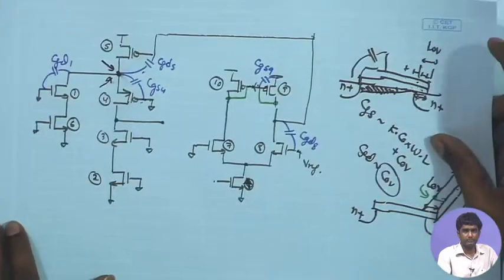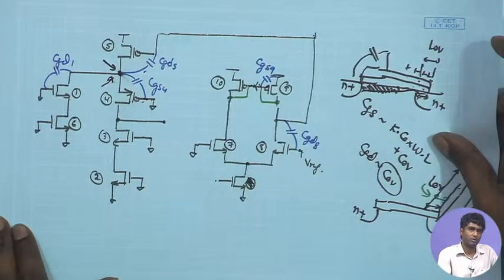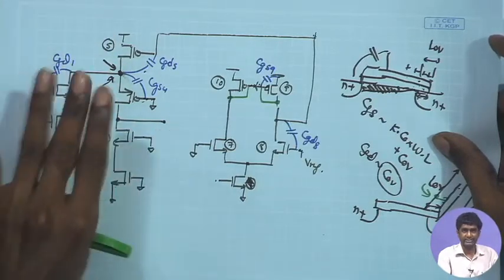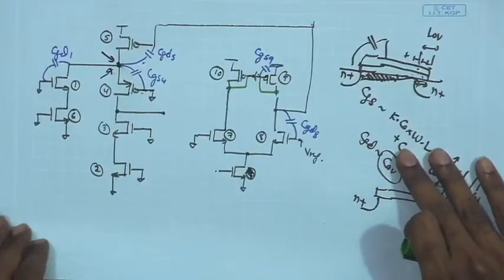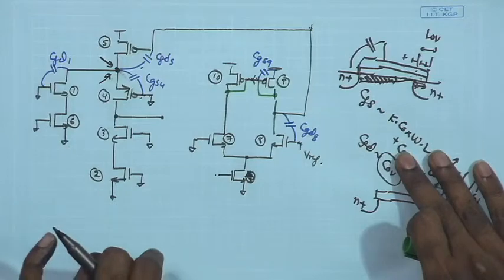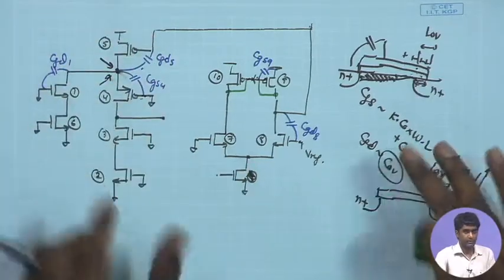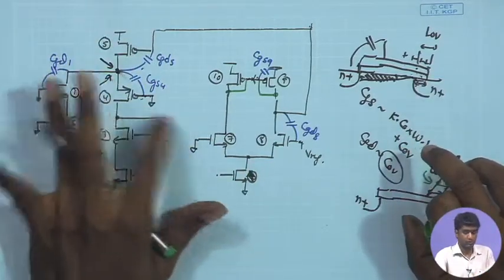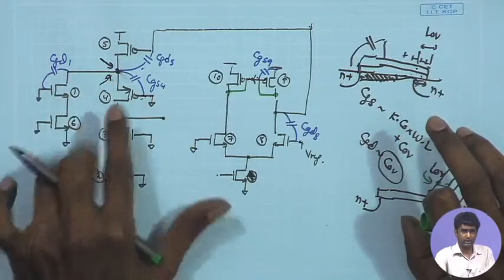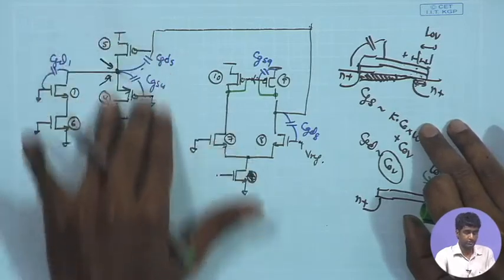Alright, so let us look into the noise analysis for the Cascode amplifier and try to arrive at the overall input referred noise and see the sizing constraint provided by the noise. For noise analysis also I can basically go ahead with the differential half circuit. Ultimately we are going to look at the two output nodes separately because they are going to have uncorrelated noise. I can look at the differential half circuit and look at the contribution of each of these transistors.